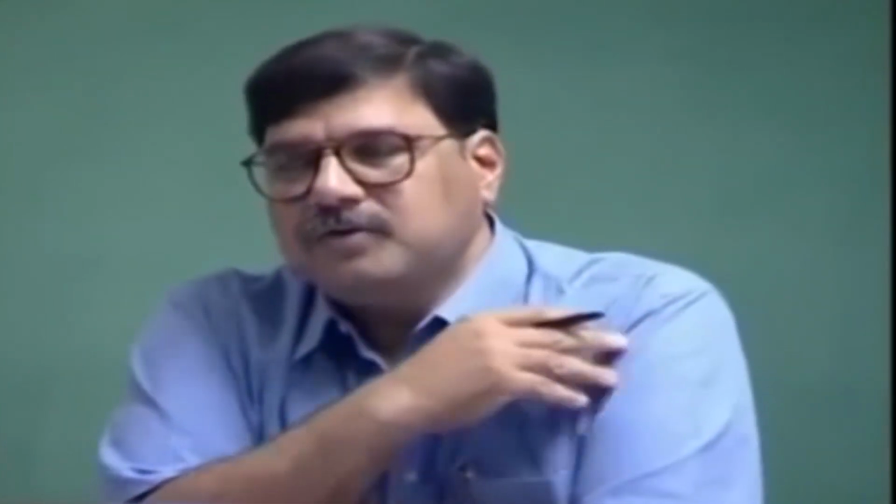So what I have done in this lecture is given you an introduction to the method of virtual work for you to appreciate the power of this method. It bypasses lengthy calculations and focuses directly on the external forces that we want to calculate. Of course, we have not included friction here because friction is a constraint force that does virtual work. You will be learning about more advanced techniques using such methods in future courses.